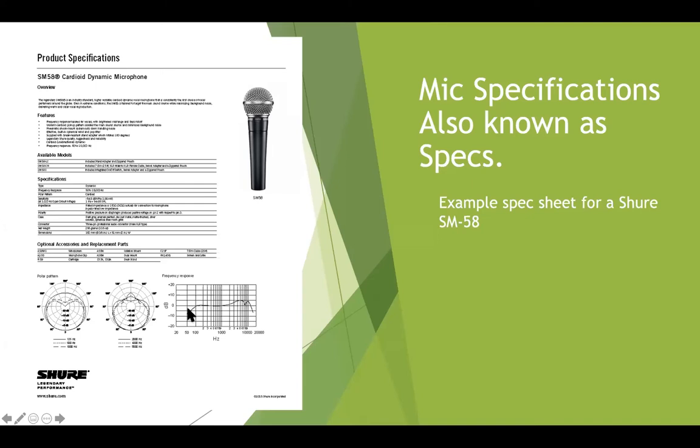It's not flat. It's also not flat from 50 to 100. Right? It takes a while before it gets to the 0 sensitivity. It's actually taking away. In other words, any sound that this records at 50 cycles is going to be down probably about 2 or 3 times normal sound level, right? So this microphone has what's called an emphasis curve, which are these little bumps here. And where is this little bump? It's right around 4,000 to 5,000. Why is that nice? Because that's a good place to have an emphasis for human speaking and singing.